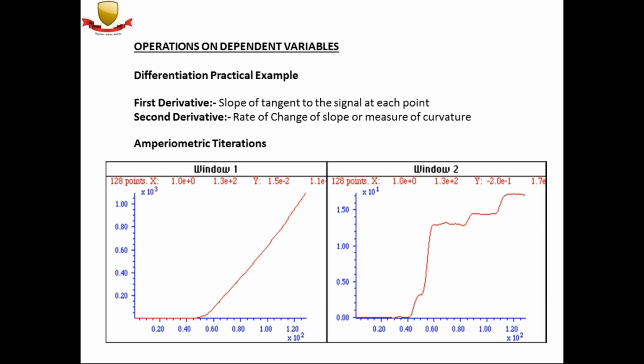Although this noise was not particularly evident in the original signal, it is more noticeable in the derivative. So I hope now you can understand the use of differentiation. It is quite difficult to find the breaks in the original signal, but once you differentiate the signal, you can clearly define the segments.